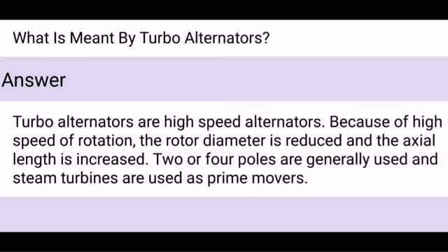What is meant by turbo alternators? Turbo alternators are high-speed alternators because of high speed of rotation. The rotor diameter is reduced and axial length is increased. Two or four poles are generally used and steam turbines are used as prime movers.